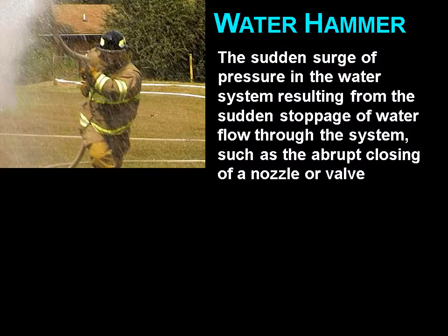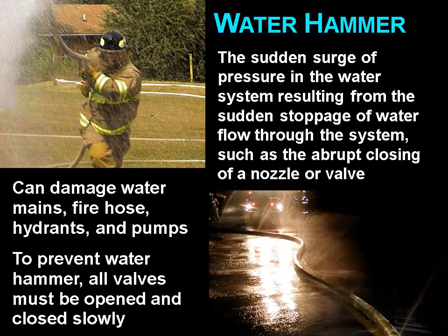Water hammer. The sudden surge of pressure in a water system, hose, pipe, or fire pump, resulting from the sudden stoppage of water flow through the system, such as the abrupt closing of a nozzle or valve. So when we do our practicals, you'll be taught to shut them down, open and close them slowly. To prevent water hammer, all valves including nozzles, hydrants, and hose clamps must be opened and closed slowly. A brief application of water fog at about 150 gallons per minute for about 1 second will not cause water hammer.